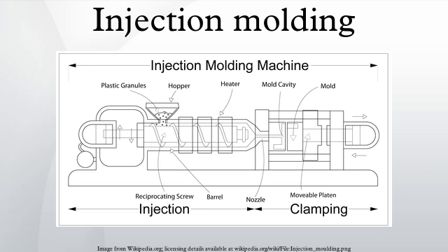Two-shot or multi-shot molds are designed to overmold within a single molding cycle and must be processed on specialized injection molding machines with 2 or more injection units. In the first step, the base color material is molded into a basic shape, which contains spaces for the second shot. Then the second material, a different color, is injection molded into those spaces. Push buttons and keys, for instance, made by this process have markings that cannot wear off, and remain legible with heavy use.